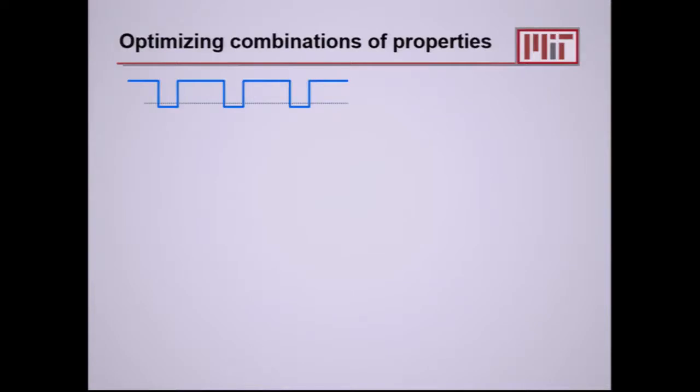So there's a lot of flexibility here. I can control the grain size, and I told you how we do it, right? We do it by changing the shape of this waveform as we're growing the coating. So we don't have to do that necessarily from one sample to the next. We can do it on the fly as the coating is growing.